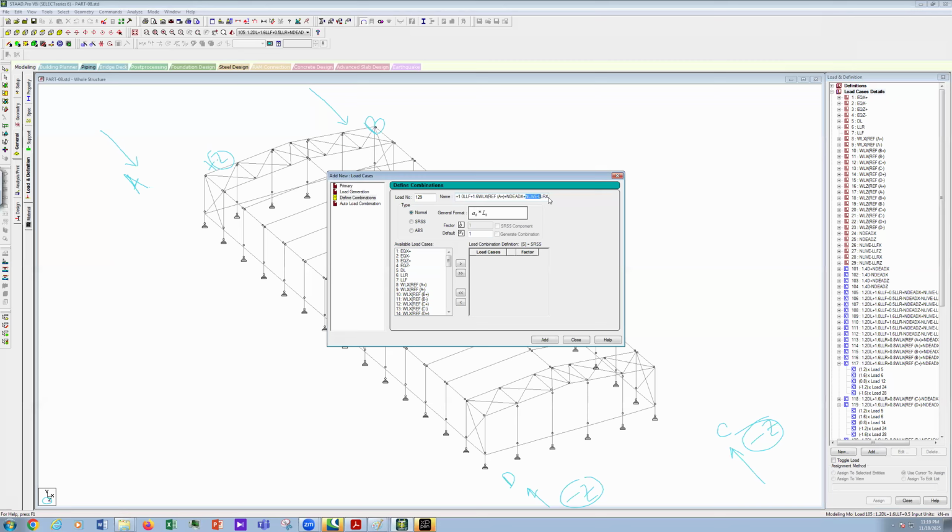This one, just copy here, copy, and just paste. You can see this N live, but this will be roof, X direction, and then plus. And then we have N live load for roof X direction. Okay, you can see here this notional load for floor along X direction. Sorry, this one for roof and this one for floor, and this is for dead load.